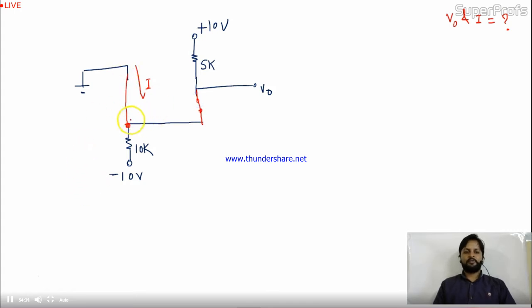Okay. When you short it, this 0 is directly coming to here and directly coming to V0. In this case, V0 is 0 volt. If V0 is 0 volt, can I now find this current I? Yes, I can. I have to check the conditions of the diodes, whether my assumption is correct or not. So I have to find this current and this current, because the diodes are connected in these two branches. I need the current direction so I can judge whether my assumption is right or not.